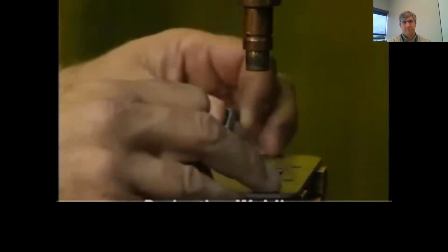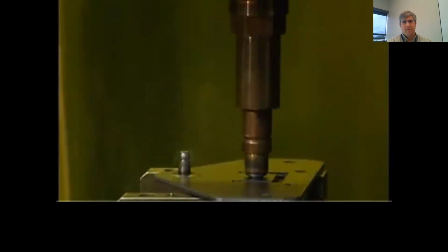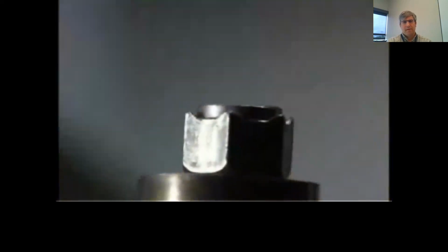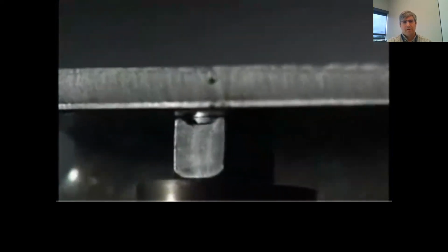In seam welding, coordinated pulses of electric current from rotating wheel electrodes produce a series of overlapping spot welds, resulting in a leak-tight welded joint. In projection welding, the welds are localized at predetermined points by projections, embossments, or intersections. Several points may be welded simultaneously.